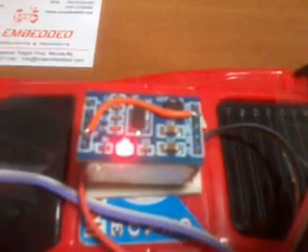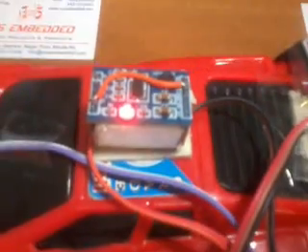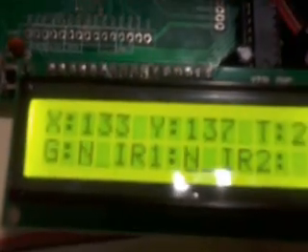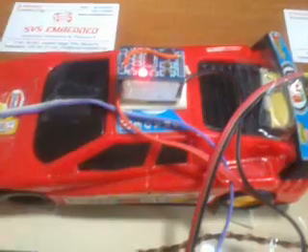Now X is shown; here we are using the MEMS micro electromechanical sensor. That sensor has an X coordinate and a Y coordinate, and those values are read through the analog to digital converter. The X axis value and the Y axis value come from analog. Let us assume it is in a stationary position. If we tilt it, the angle of the momentum changes, and the analog voltage levels will be different.